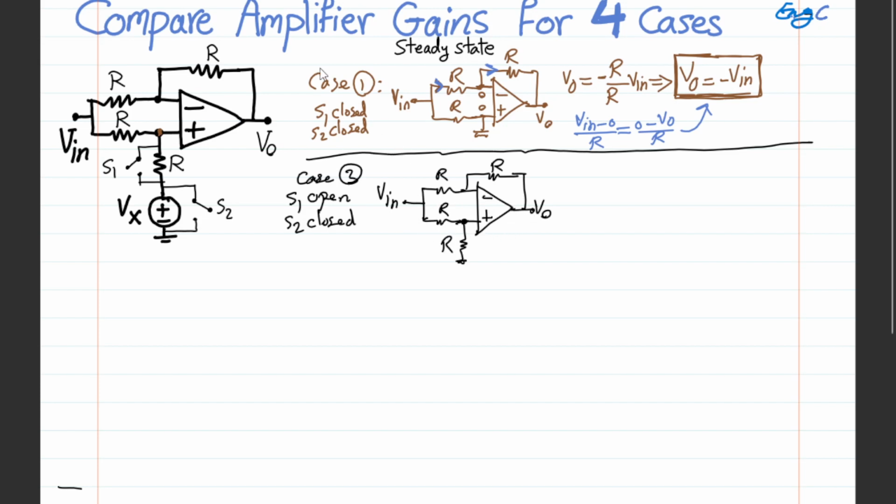But one thing you can quickly do is use the formulas. Vout equals, just to show you the quick computation way, the inverting amplification contribution like above: negative feedback resistance R divided by input resistance R times Vin.